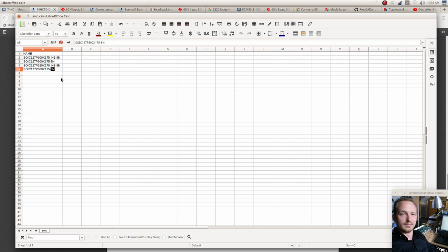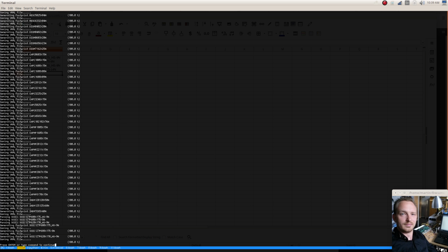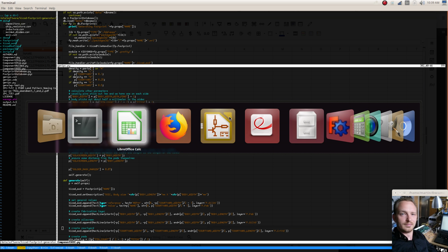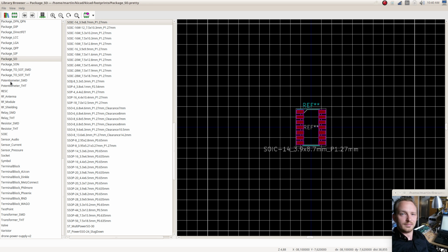And it has no pad underneath, so it's going to be 14 pins, and we have normal density. We rerun the scripts, and then we can go back here and re-add this custom footprint, or actually just add it side by side.